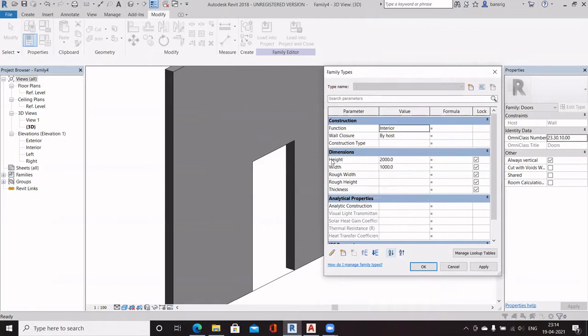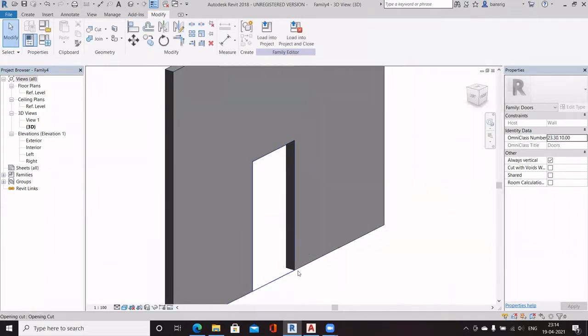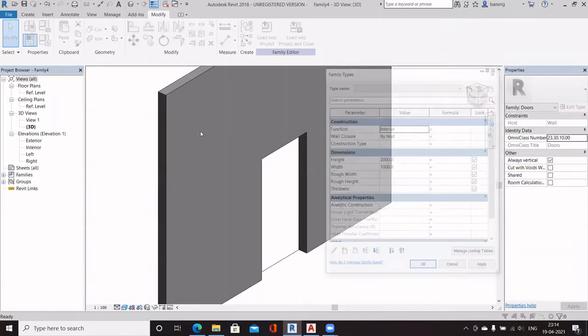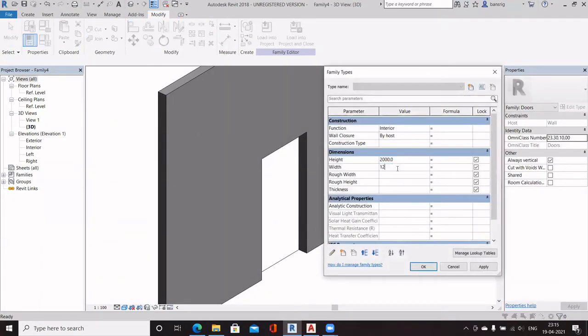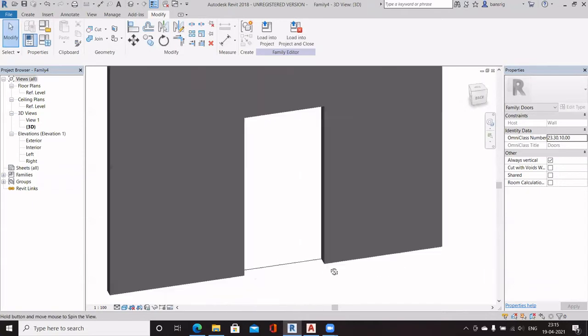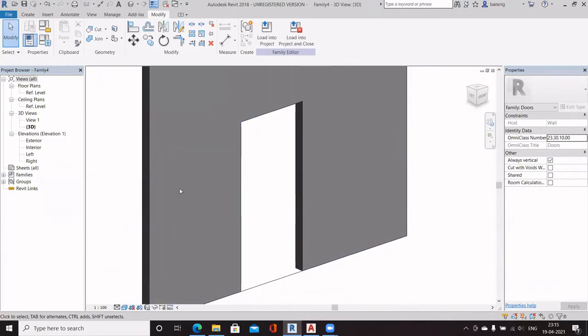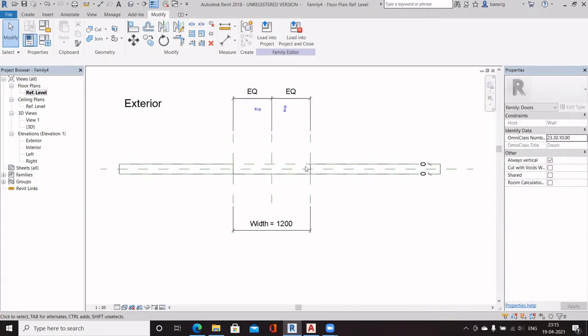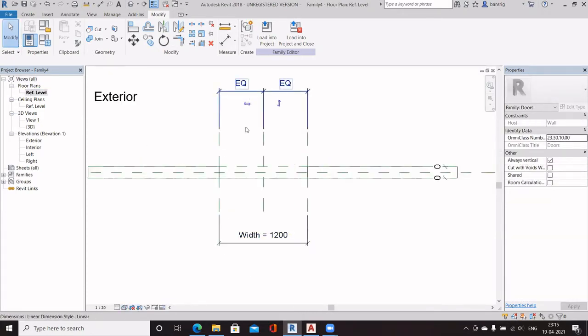Apart from that, there are width and height parameters which I need. These parameters belong to the opening that has already been created. So before starting a family, you can adjust these height and width parameters to the ones that you need, and make sure that your opening widths and heights are correct. Of course, because these are parameters, you can always modify them and edit them at a later stage of the family. There are also a few reference planes provided to you in the template, which we are going to use in our project.